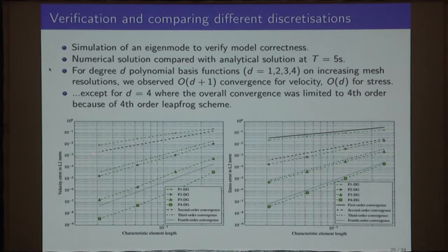So on the top here, this is the first order scheme. Oh, and this is different mesh size. Sorry, I should have explained. This is the characteristic element size. So the mesh is fairly regular. All that we're doing is reducing the element size. And then if the theory is correct, we should see the order of convergence by measuring the slope of this line.